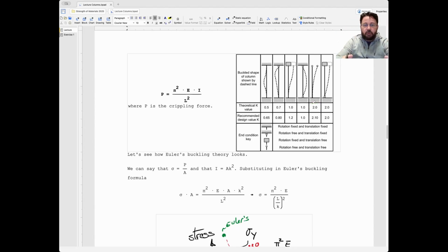So how do we choose what kind of joint we select? Well, let's guarantee the stability of the structure by the equilibrium of it, logically. But also, if you have the freedom of choosing, there are other parameters, like the effects on other parts of the structure. But you know that if you work with fixed ends, let's say columns, it's going to be prone to resist more creeping load or more axial load than the others because of the variation of the effective length based on the type of joint. So you're getting that whenever you're designing a column, the ends matter. It's not just that you cut and release the column from the ends, from the beams, roof, or floor. Ends matter a lot.